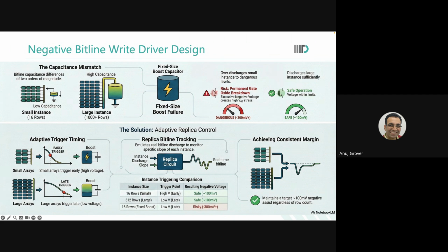If I do not allow it to discharge for the entire time, this voltage level will remain at, let us say, 0.6 volts. So when I say this, let us say this capacitance is 1 picofarad, just for some funny calculations, okay? 1 picofarad is what the bitline is typically called. So what is the total charge that I have on the capacitance on the bitline?